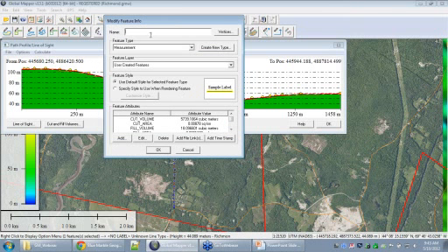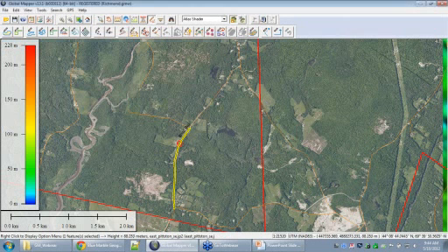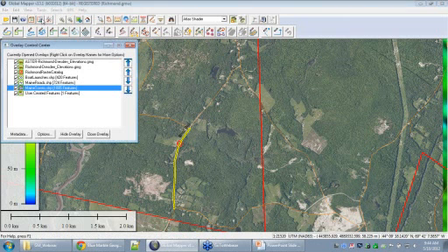Because we selected to create a new feature from that, we can actually add some attributes to that. You'll see all of the cut and fill area are being pasted right in as the attributes on that line. And we just need to give that a name. I'll call this our road bed. And then we have a new line segment that is drawn on our map representing that portion of the roadbed project, and we can save that out as its own discrete file.